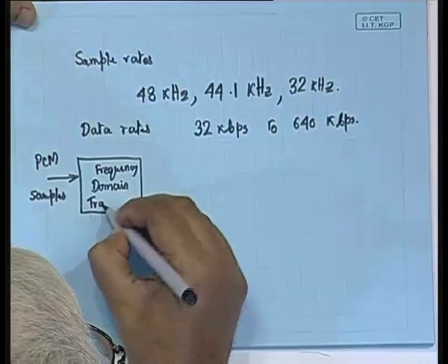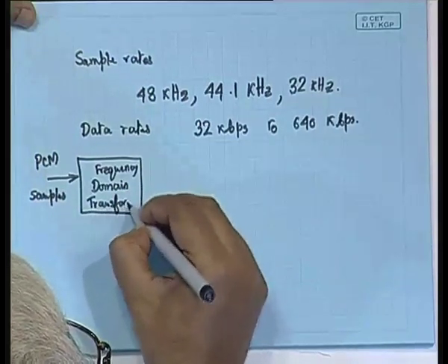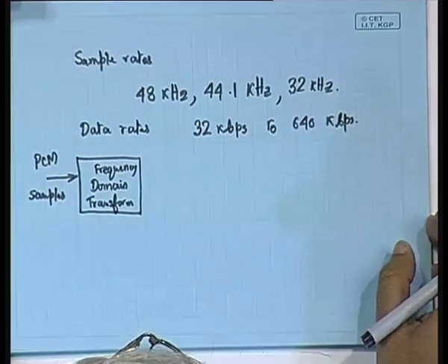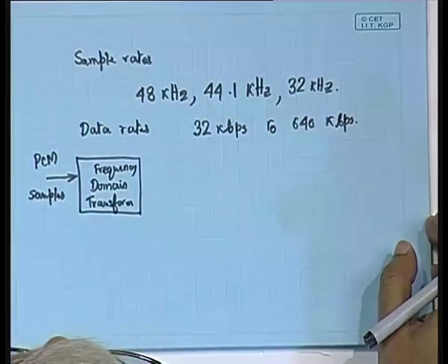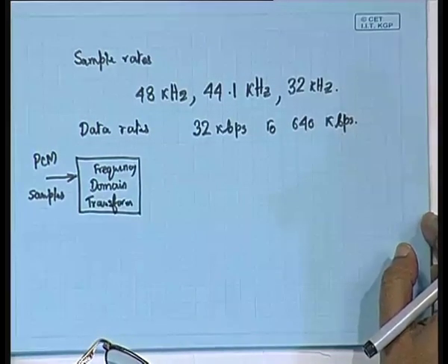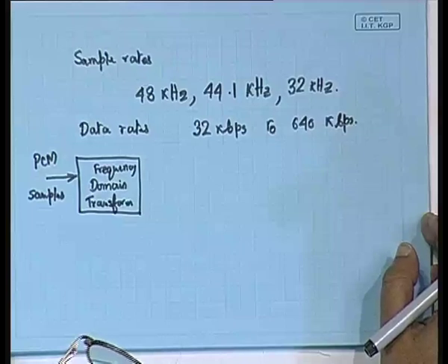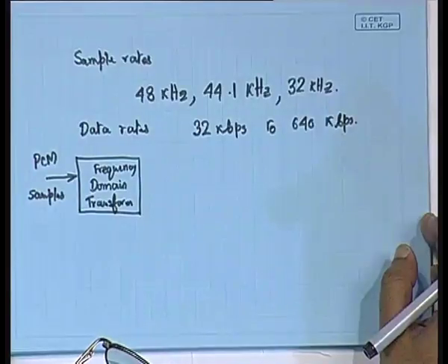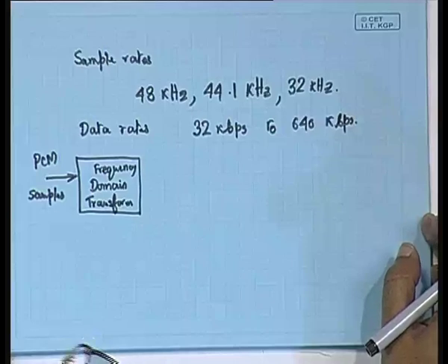I was just now saying that here the FFT was performed in order to identify the tonal components, but of course, FFT involves a complex computation. So, computationally it is quite involved, and that is the reason why we had seen that in the case of images and videos, we were adopting the discrete cosine transform, which has a real kernel.